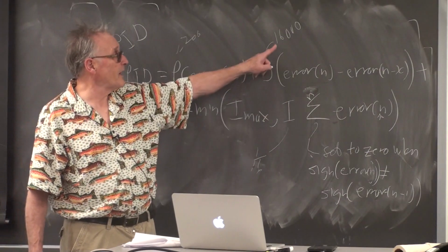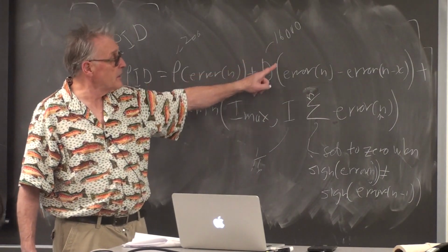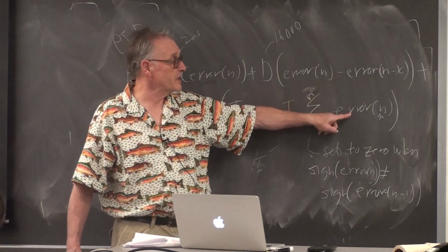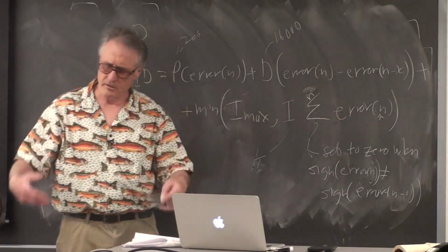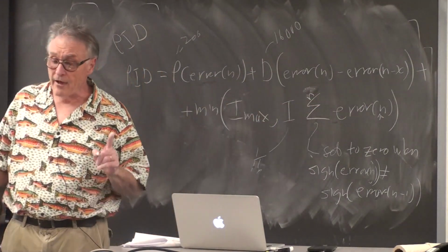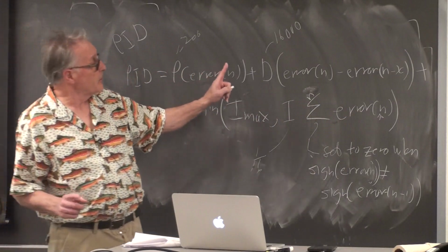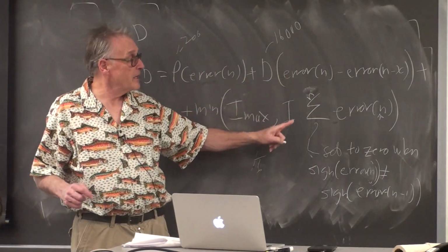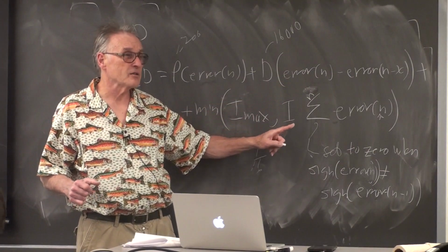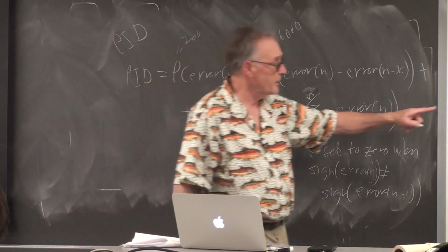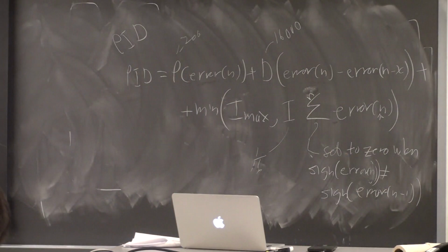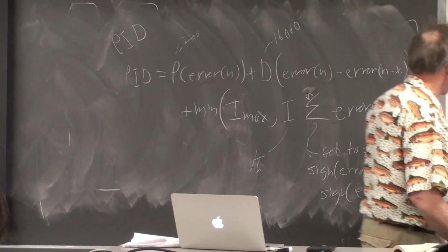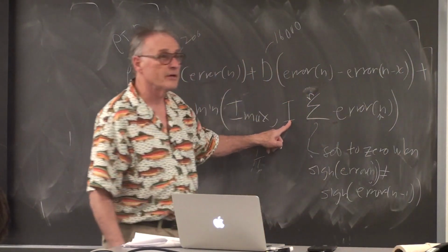That's a small value compared to 16,000, but remember this is differencing and this is summing, so it's hard to scale them all. You're going to have to get these two correct, get it fast, and then if there's a bias towards underperforming here, towards being a little bit too low below the desired, add in a little bit of integral term.